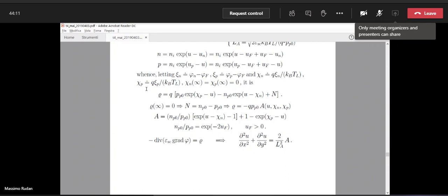In this case here, we are considering only the situation in which the channel is fully formed. So in this case, we have a large and positive gate voltage because we are considering the N-channel transistor. So we have many electrons in the channel, but we don't have practically any holes because the holes have been pushed away from the interface. Okay, so we have just a layer of electrons, and then we have the space charge region in which the charge is essentially due to the dopants.